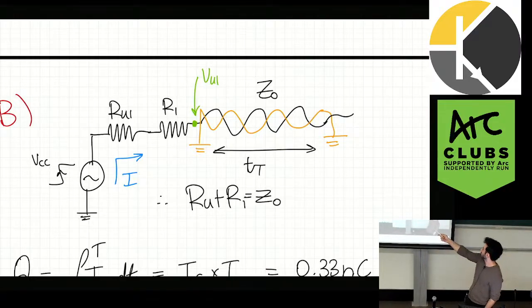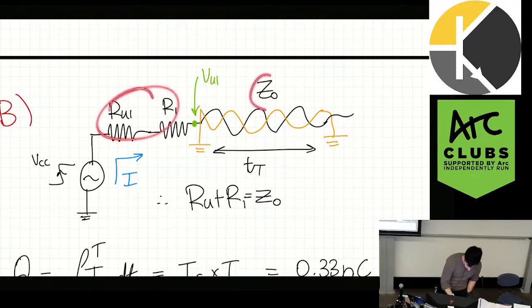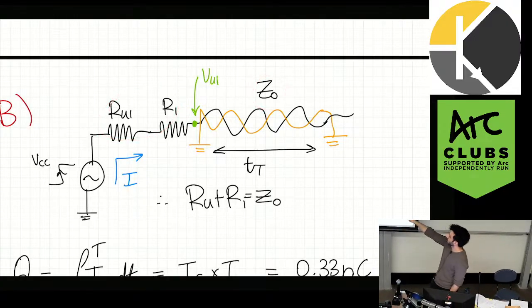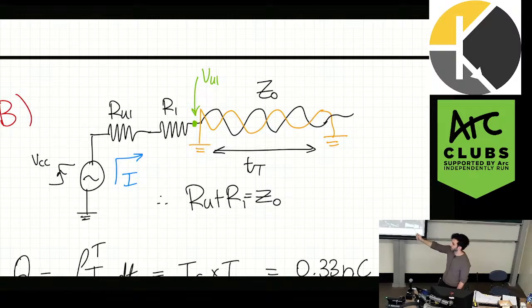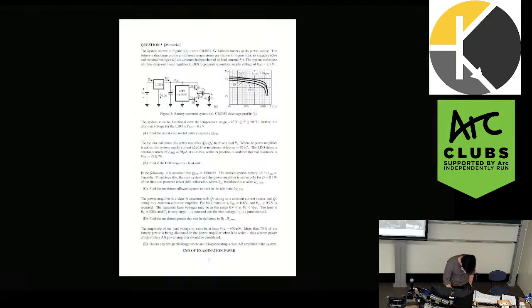It's going to be VCC on 2 because there's a voltage division between those two resistances, which is Z0. Because this one and this one were perfectly matched, it's like a voltage division by 2. That's why we start at VCC on 2. But VCC on 2 is also sent down the transmission line and comes back. And that's why after 20 nanoseconds